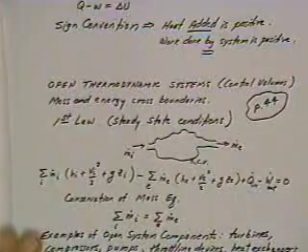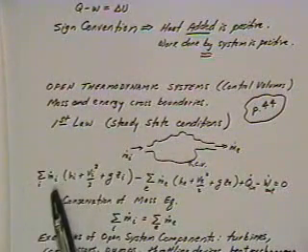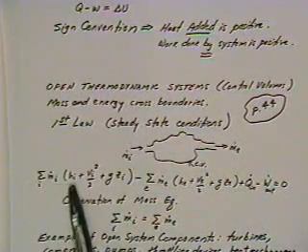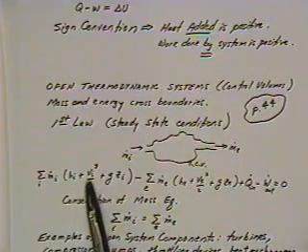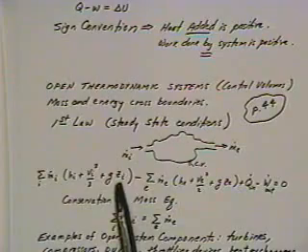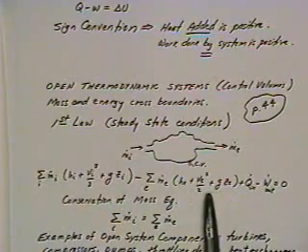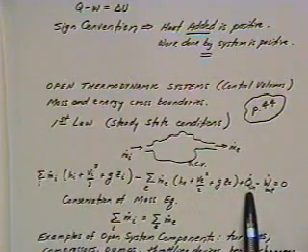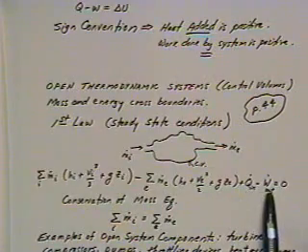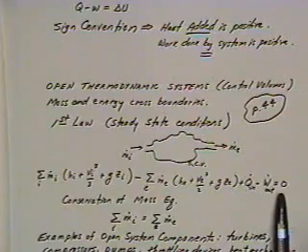and so the complete formulation of the first law says that all of the enthalpy, kinetic energy, and potential energy changes for our system, plus the heat transfer into the system, minus the rate of work out of the system, is equal to 0.